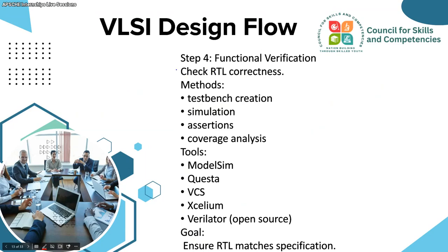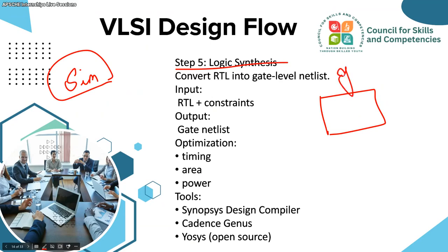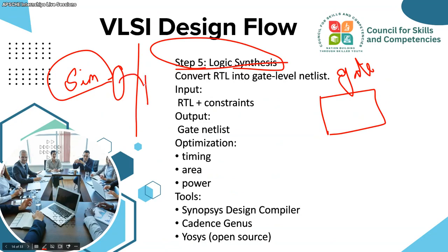Now the logic synthesis. In functional verification we are able to simulate and check it. Now we want to convert that into the exact gate level. How to do that? That is the synthesis part. Simulation is different; synthesis means you are converting that code into something at the gate level.